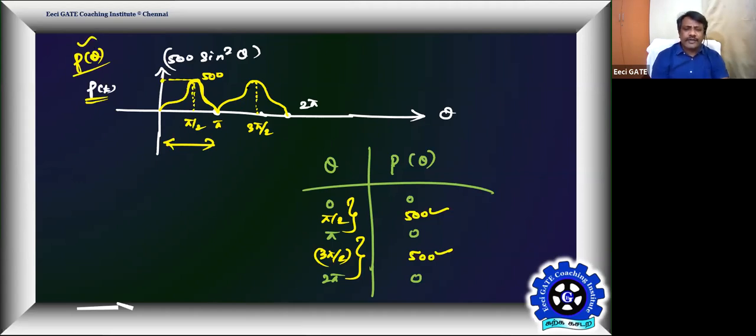So if a signal has T as its time period, then for the power delivered, the time period becomes T by 2, therefore the frequency of the power delivered becomes double that of your signal frequency. Getting everyone?